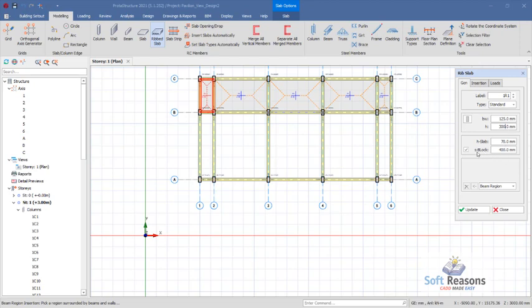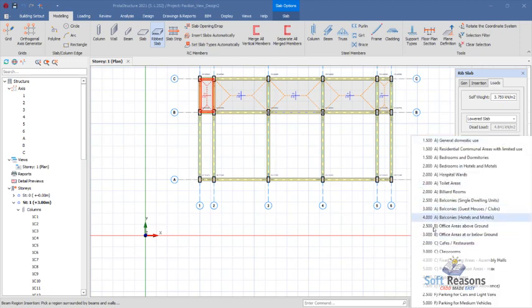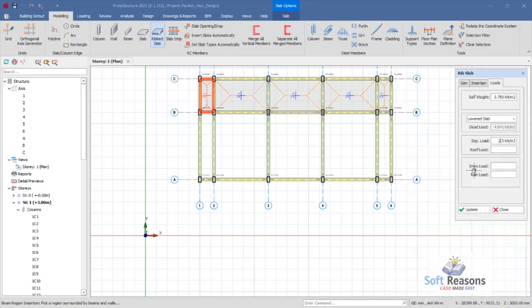Alright, so for the X blocks, which is the spacing right there, we consider that to be 300 right there. Then for the edge slab, which is the little slab thickness on those ribs, you have it to be 50 right there. Okay, so we check the loadings right there. So over here we consider lower slabs, just as we did in the other provisions. For the imposed load we used 2.5 right there.